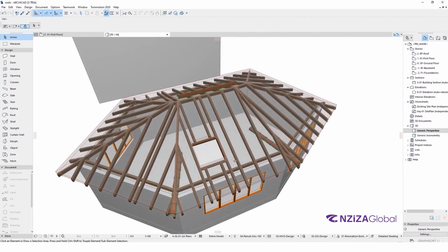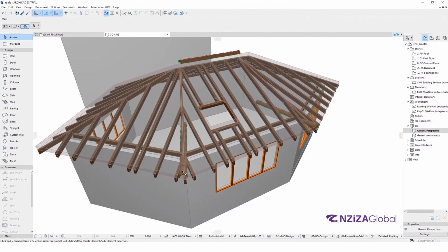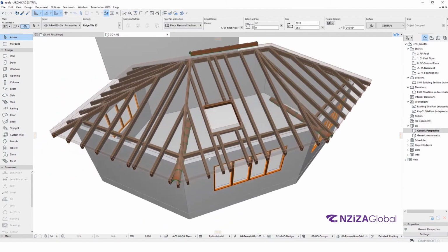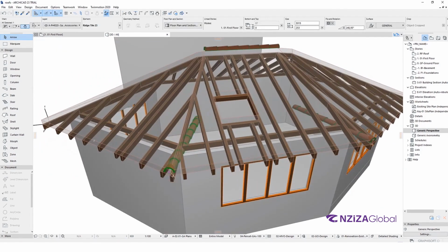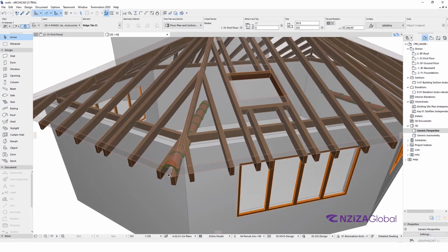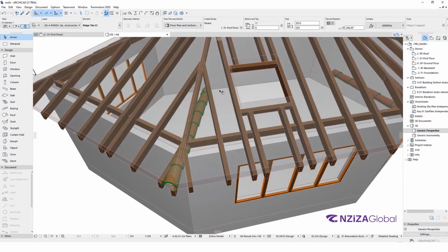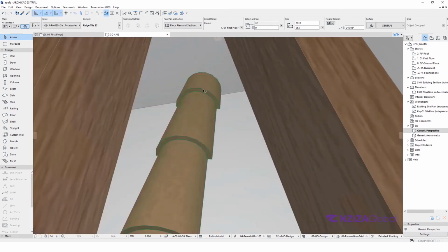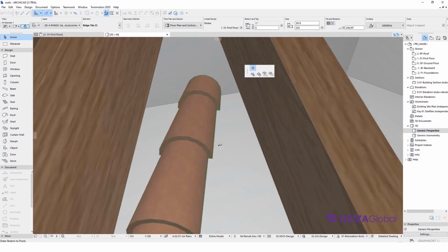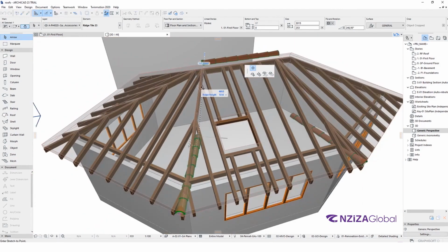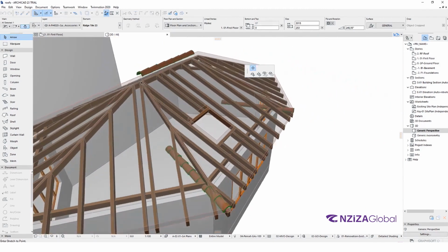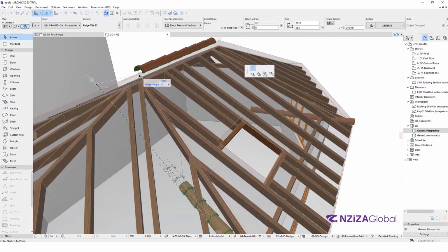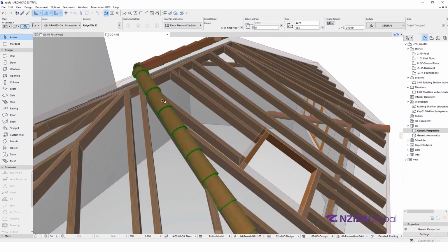As you can see, we have 3 tiles. Select one of them. As you can see, we have pink dots on the edges. We have one more here. It's barely seen, but it's here. Click it. Make sure you have selected the move node, and click the top point.